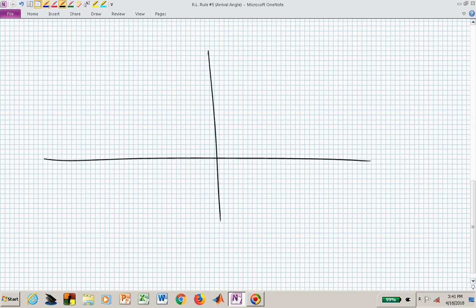Let's just resketch our picture. We have our zeros here. We have poles, 3 different poles. We have a pole zero excess of 1, so we know we really only have the one asymptote going off to minus 180. And now we can start calculating these angles. Let's say that we call this angle theta sub z sub 2.